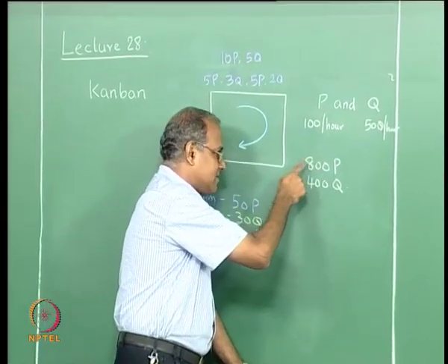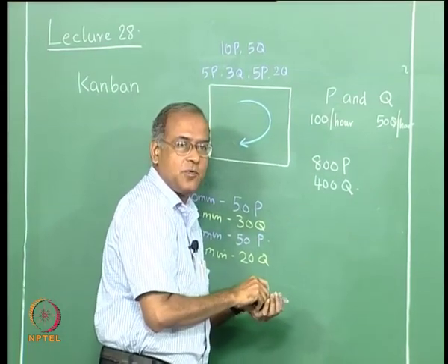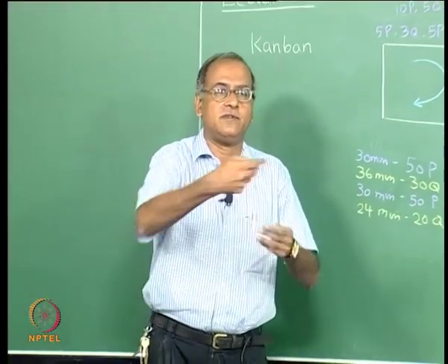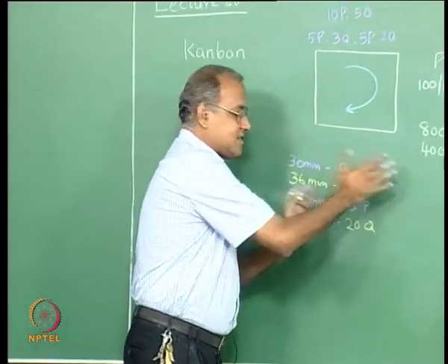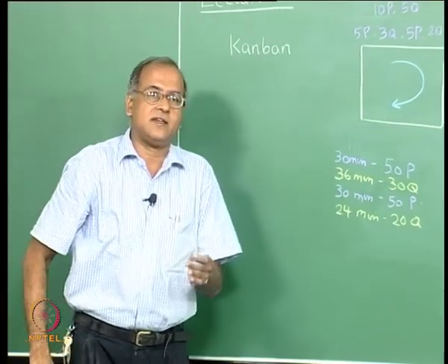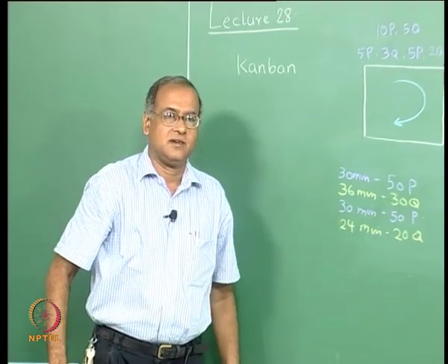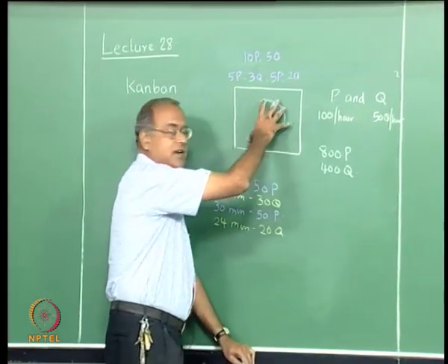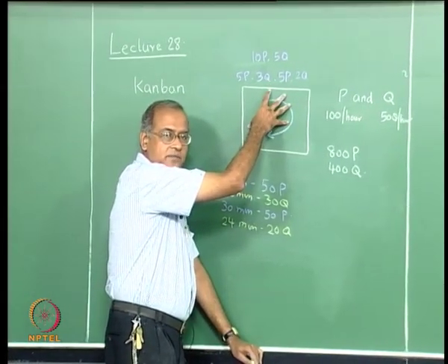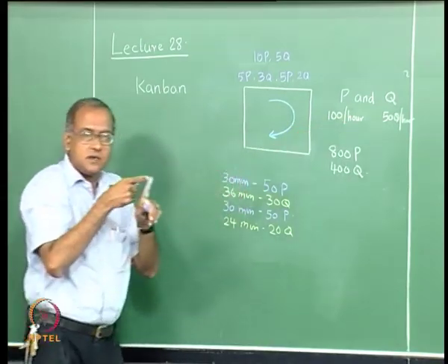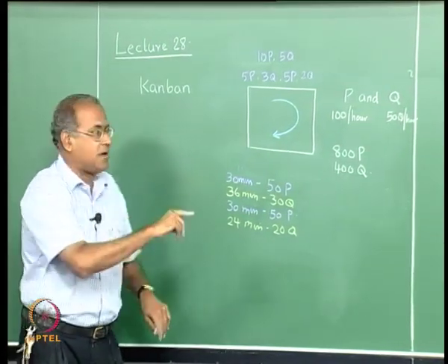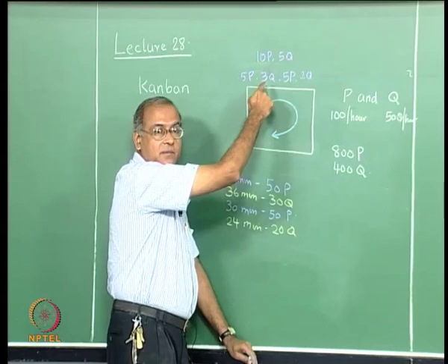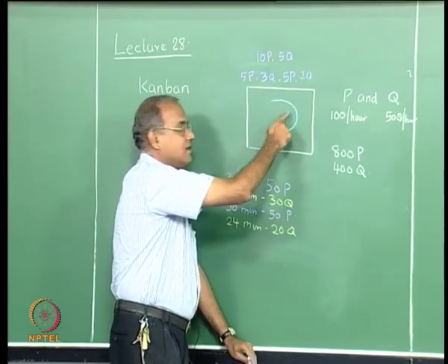I could have made this as something like a capacity to produce 100 per hour, but a setup of 10 minutes or something like that. I could have adjusted this calculation, but the fact is, if I have larger changeover times, I will not be able to bring down this inventory to the extent I can. So, by constantly moving towards quick setups and quick changeovers, I am trying to release as small a quantity as I can, so that the inventory here reduces.